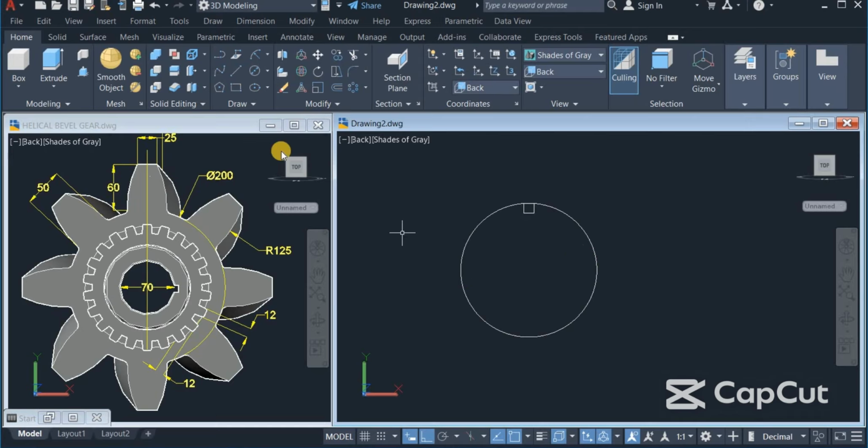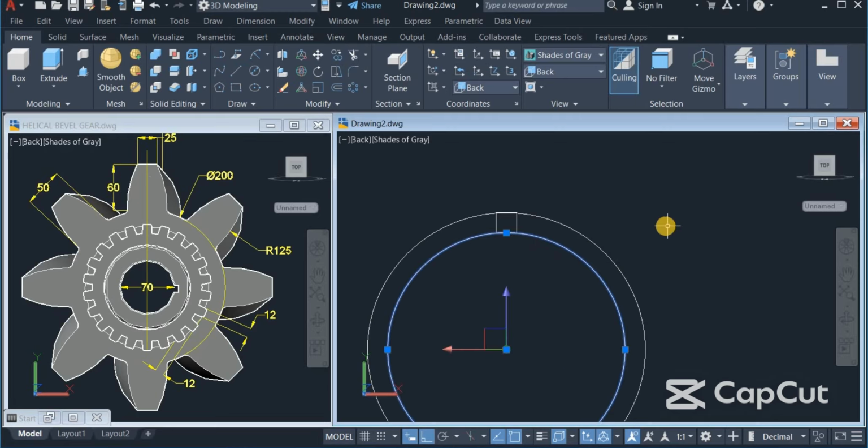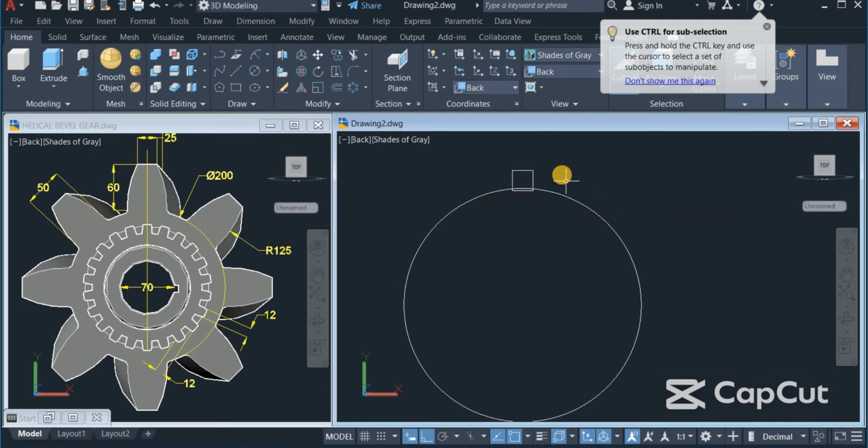So now I'm going to draw another circle again. Go to the center, draw a circle to touch this portion. Okay. So I can now clean up this. Alright. I'm going to move this one down by 1 mm. Click on this move. Move. Put it down by 1 mm. Alright.